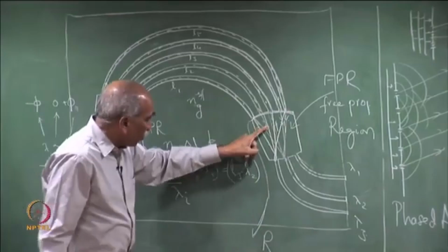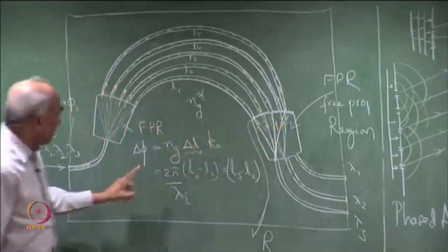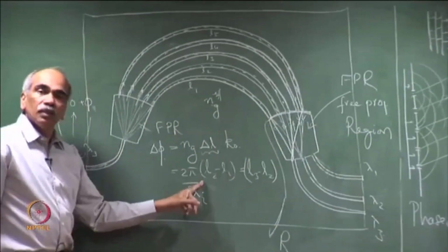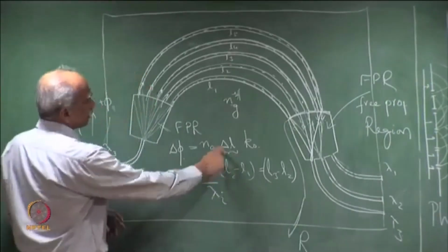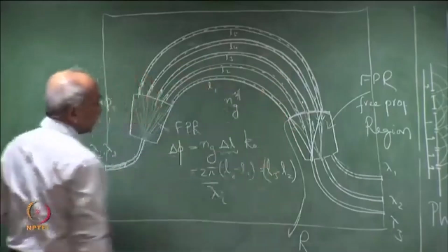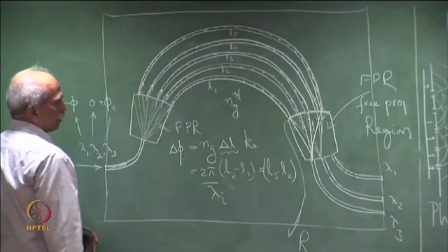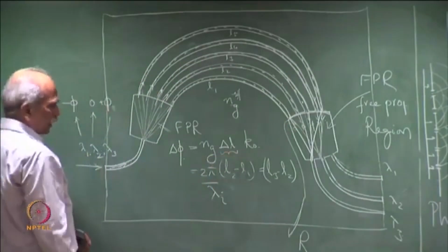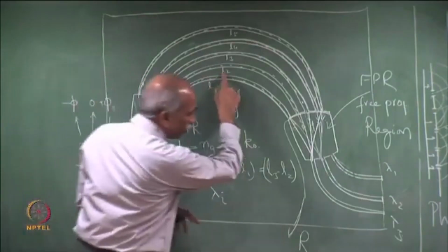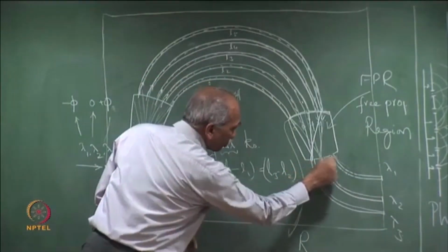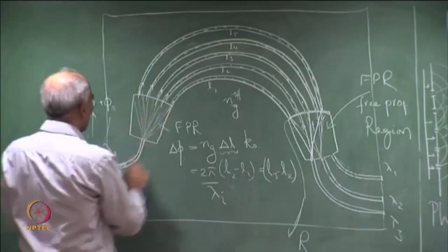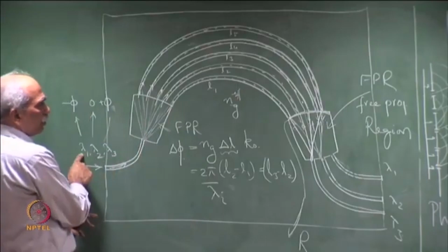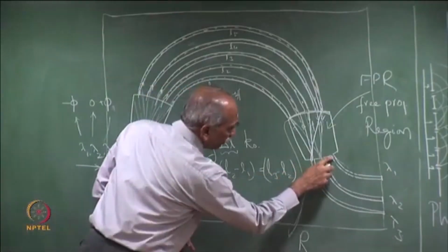Now, phi or minus phi is determined by the wavelength. So, one can choose delta L, that is the structure here design. Delta L and the positions of the output waveguides are chosen such that at wavelength lambda 1 all of them focus here.